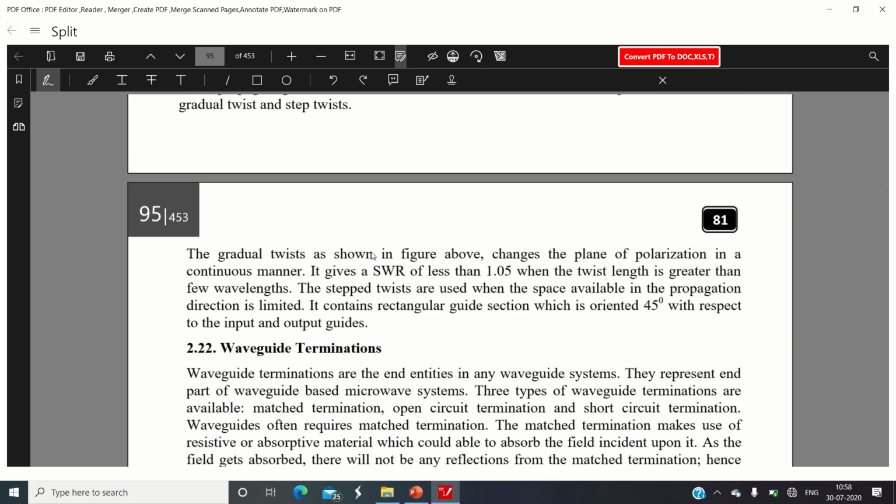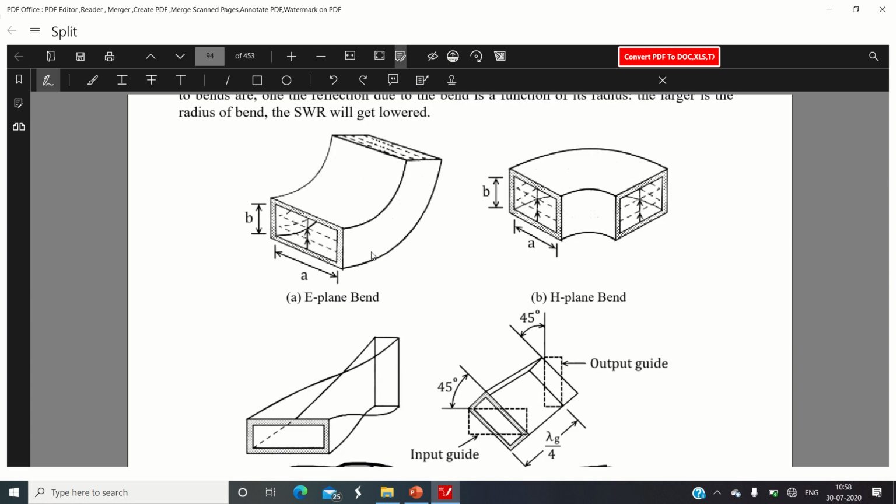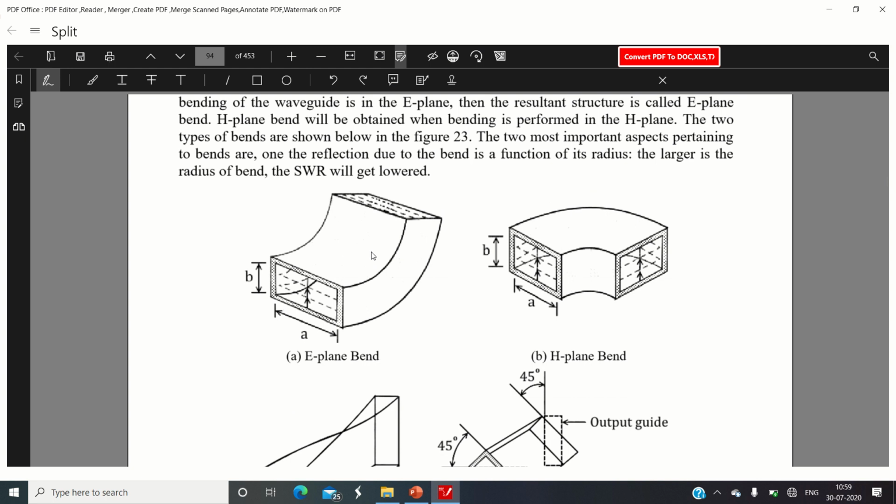Today we discussed the investigation of the field components of rectangular and circular waveguides, whose derivations we already did in our previous lecture. We went into greater detail on the mode field patterns, and afterwards we saw the resonator circuit, how it is constructed and why it is called a special case of a waveguide.